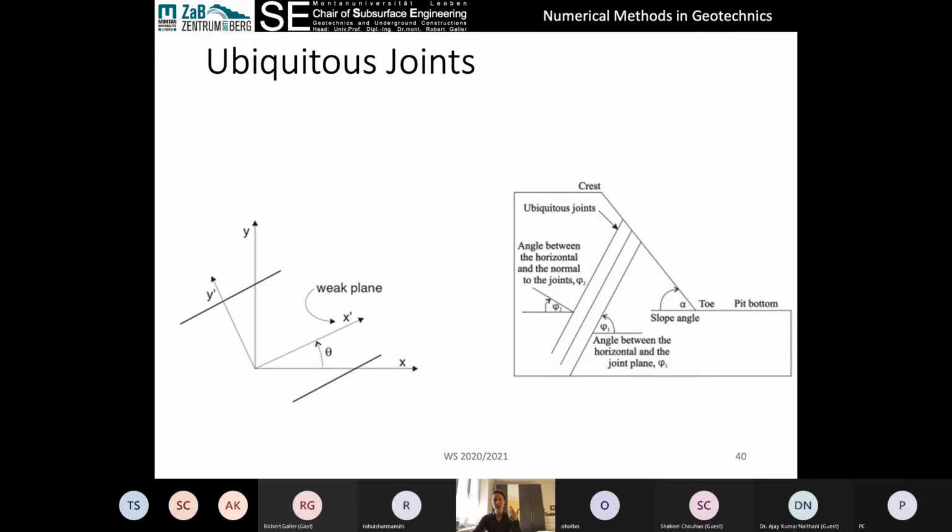Then it will solve a second time on a plane. So it'll solve the normal and shear forces on a plane to see if that plane has failed. And if that plane has failed at that particular angle, then it will say that that element has encountered planar failure on the ubiquitous joint. So there are no discrete joints.